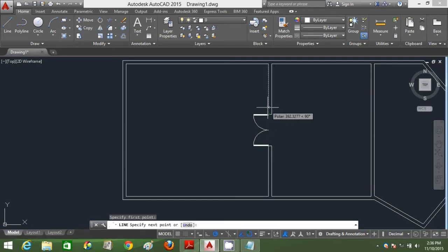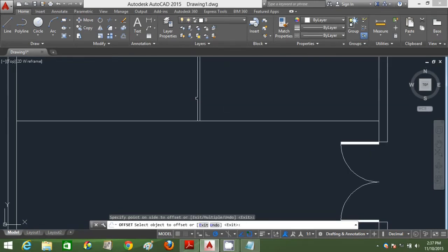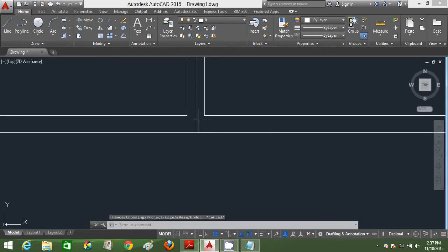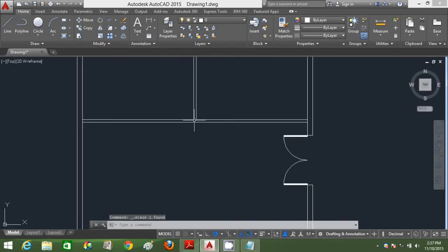Right? So I'm just gonna mark one reference line here by 500 mm and just draw this line to create the executive's office. Alright, so offset this by 50 mm. So I'm using that line as my center line. And then type O, enter, type 100 and offset this line inside. So type TR and enter twice. Trim the unwanted portions. Select the center line. I'll trim out this portion first, and then select the center line and delete it.